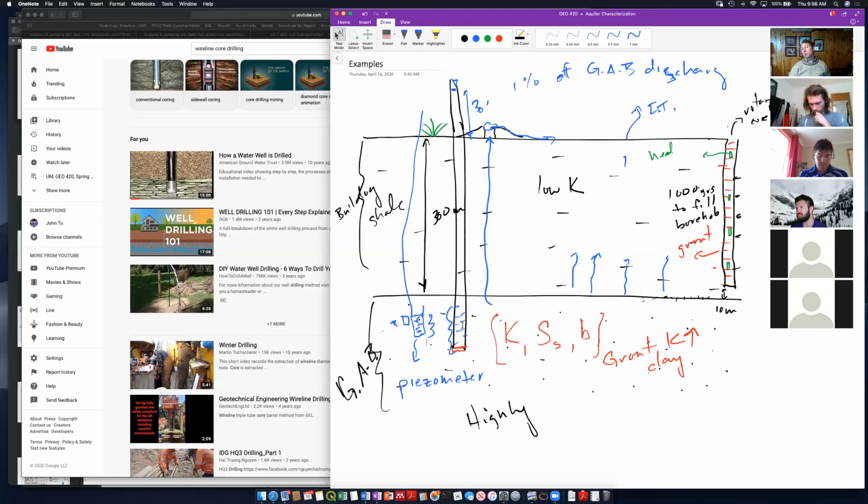Similarly in water, we can pull core. We're doing a bunch of drilling in bedrock in the mountains, and we want to have screens where there are fractures. So we'll look at the cores, figure out where there are fractures, and then say, okay, we want to screen over this interval. So you characterize as you go. That's the most common.